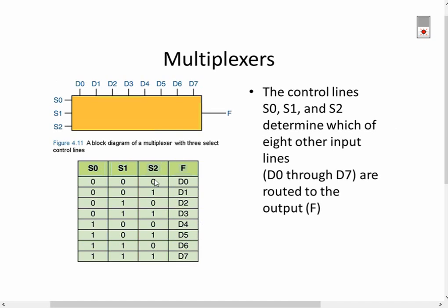So if I were to look at an example of a multiplexer, you'll notice here that D0, 1, 2, 3, 4, 5, 6, and through 7, these are all potential inputs where I have these bits off to the side. S0, 1, and 2 determine which one is actually going to be selected. So if you think about it, in binary, 0, 0, 0 produces 0. That's one combination.